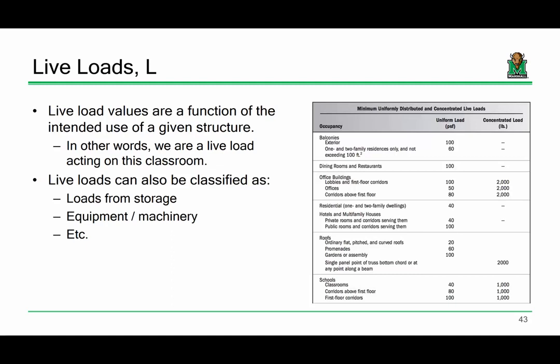Live loads are also pretty easy to determine depending upon your type of structure. You do need to perform live load reduction, and we'll talk about that here in a second. But live loads are dependent on the type of structure that you're looking at. A term that I like to use is occupancy. They are related to the occupancy of the structure, what the structure is being used for.